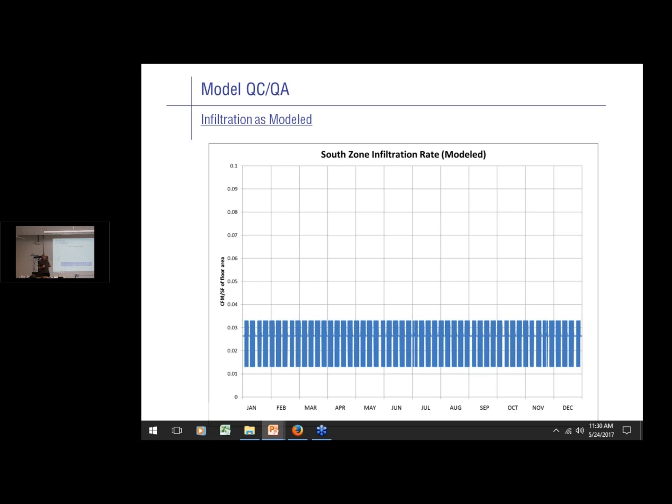Something's driving the temperature in the wintertime down below the night set point, or in the summertime up above it. Typically it's too much infiltration moving through your zones at night. You've got to check it. You've got to verify it. I mean, you can do it in a kind of crude way by extra review of your inputs, but ultimately this is a much faster and more effective way, because this is what the models actually do.